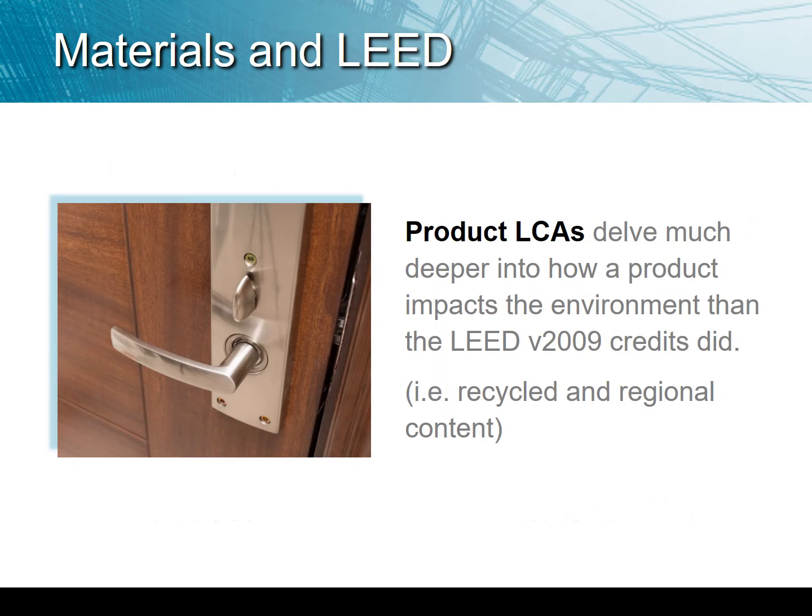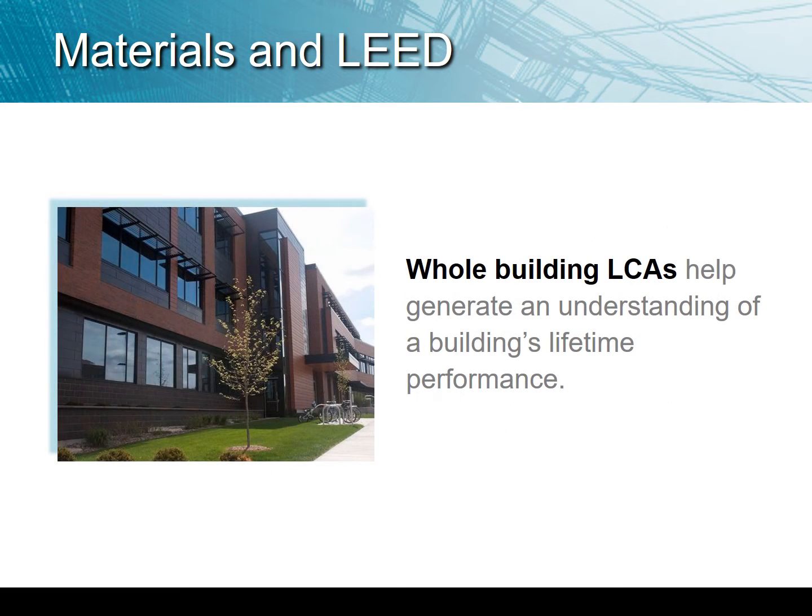A product life cycle assessment delves much deeper into the actual impacts of how a material affects the environment than the rudimentary ways that the LEED version 2009 credits, such as the credits for recycled or regional content, did. LCAs incorporate recycled content and often the location within a broader range of factors which we will go into soon, in order to create a more comprehensive picture of the entire environmental impact of that product's lifespan. Whole building life cycle assessments help generate an understanding of a building's lifetime performance as related to the materials chosen.